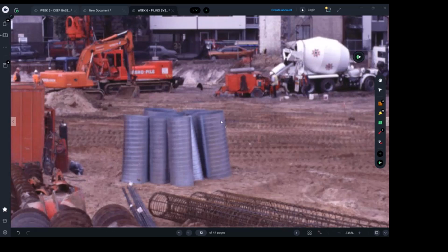And then while we take the soil away, we're going to place this because it's going to provide a temporary propping for us within that 1 meter. And then we can go back and use the CFA to go into the 9 meters. So that's if the soil we find does not really withstand itself at the top.